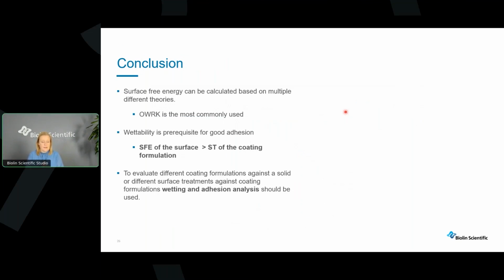So I think with this I am coming to the conclusions. Surface free energy is something that we cannot measure directly, unfortunately. We need to do it through contact angle measurements, and then we need to apply a theory that allows us to get access to this solid-liquid interaction, and the most commonly used theory for that is the OWRK theory.